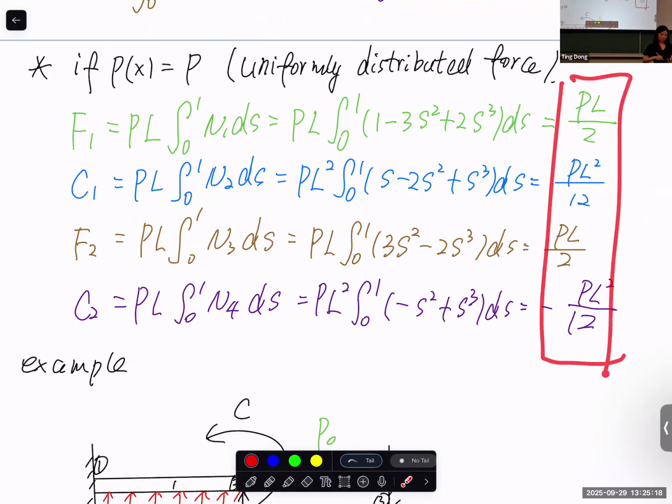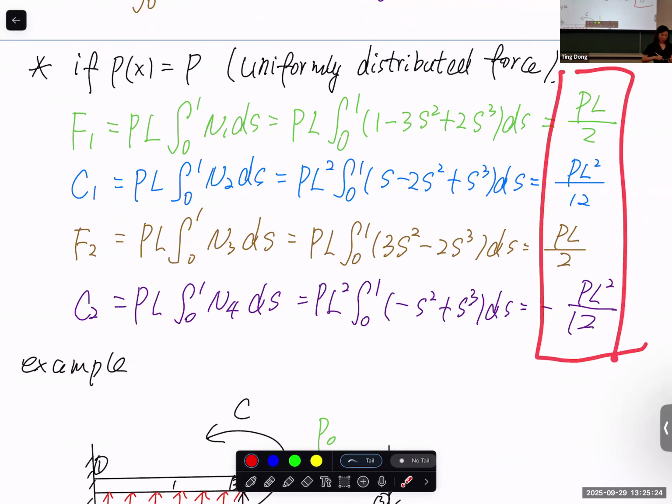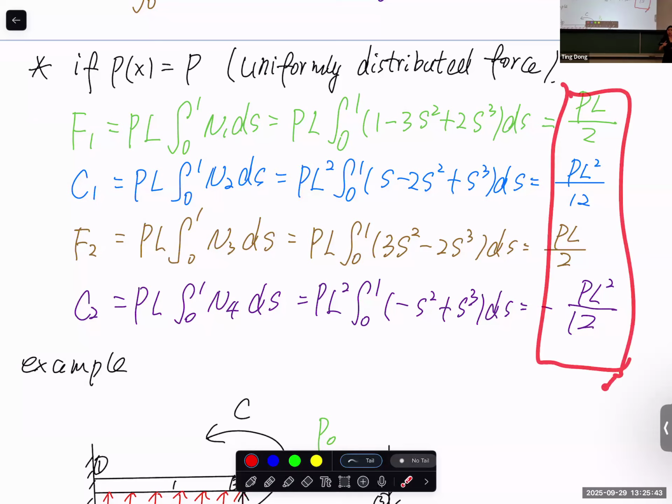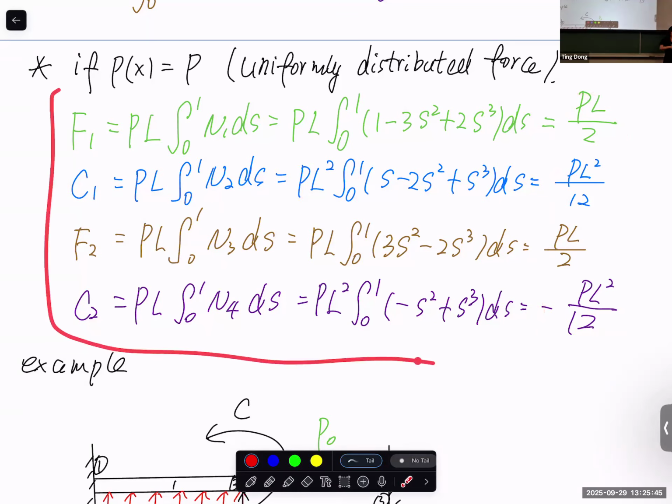So what is the equivalent nodal force for? Yes. So let's do it one by one. Let's talk about the cancel out later because there's some tricky part. So let's say for element 1, we just plug in this P naught, right? For element 2, since it's downward, there's a direction in it, so negative P naught throughout, and negative, negative, positive. Make sense or not? As I said, everything we derive in class, you can use in your calculation directly. You do not need to go through the whole calculation again.